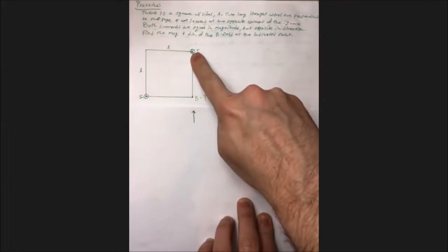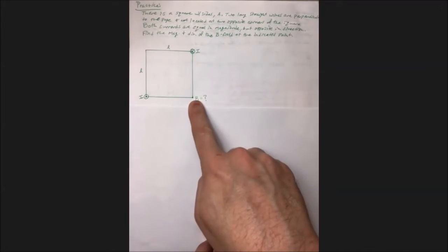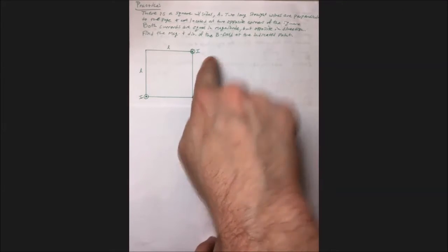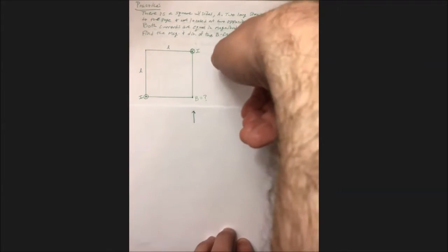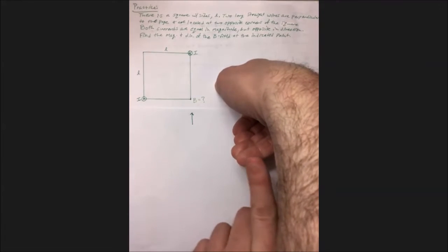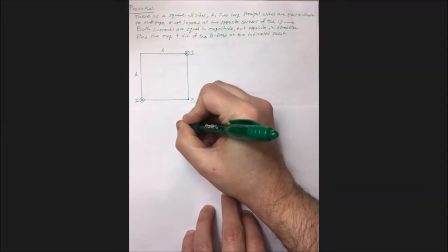So our magnetic field lines on that side are going to be pointing up. All right, now let's do this one, okay? In this case, the current vector is pointing into the page, so we're going to point our thumb down, and we're going to curve our fingers. This point right here is on this side of the wire, so that means we have to curve it all the way around until we get to this position. So my field lines are going to be pointing to the left. Okay? So we have something that looks like this.